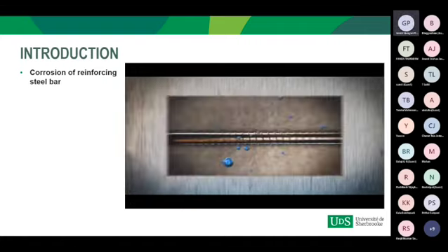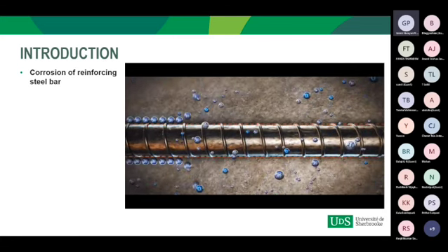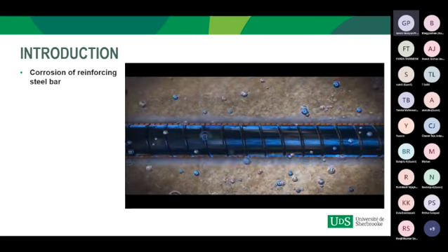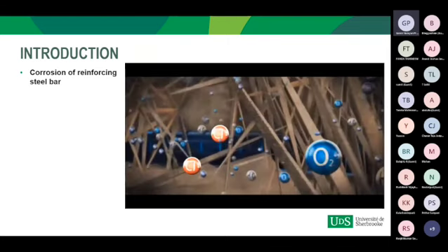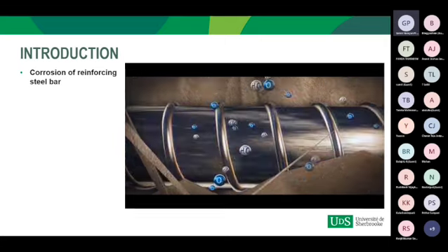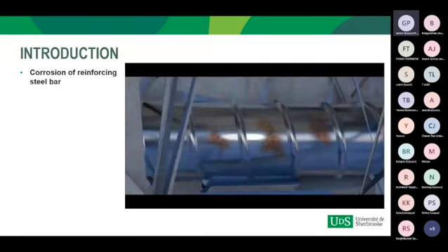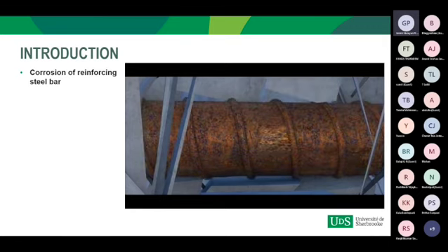The corrosion of the reinforcing steel is the major cause of deterioration in concrete structures, and the alkaline environment of concrete, which has a pH value of 12 to 13, provides a protective layer against the corrosion of the steel. However, the presence of chloride ions in de-icing salts and seawater reaches the steel reinforcement through minor cracks, and with the availability of moisture, chloride ions exceed the threshold limit and can induce rusting of the reinforcing steel.